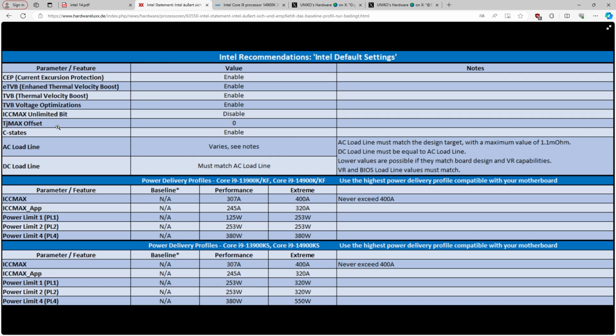I'm not too concerned if you have 1.45 volts at low load and then there's a transient spike upwards from that, because the voltage isn't going to get that high. And at high load, you're going to have 1.3 to 1.2 volts, and sure, you're going to have a bigger transient overshoot, but you're starting at a lower voltage, so it's still not really going to be a concern.